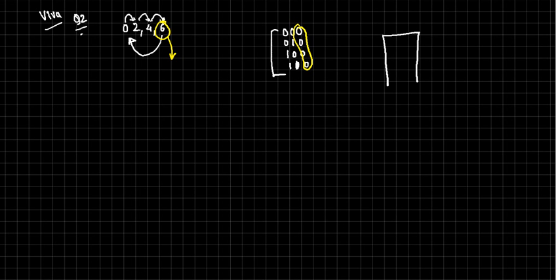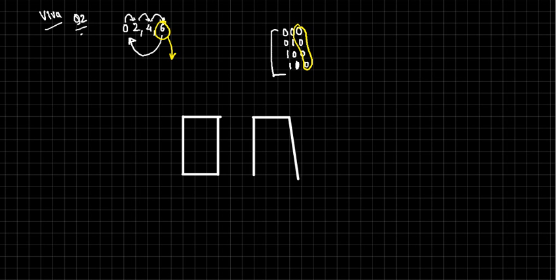Now this is an up counter, right? I have a choice that I can go for synchronous or asynchronous. So I am just going for a simple ripple counter. So I would require 2 flip-flops. This one is the LSB, right? Just because we are using only 2 flip-flops.